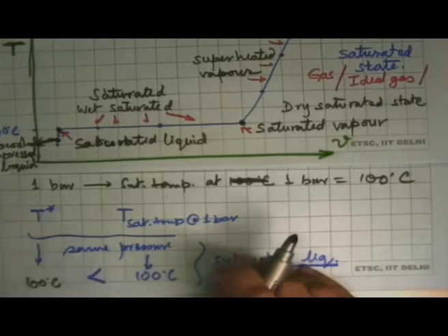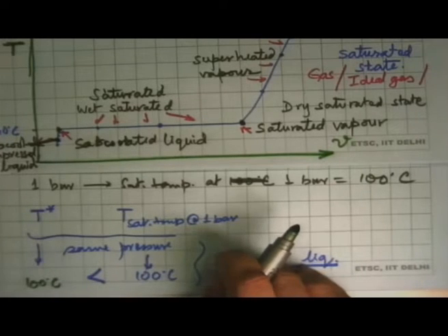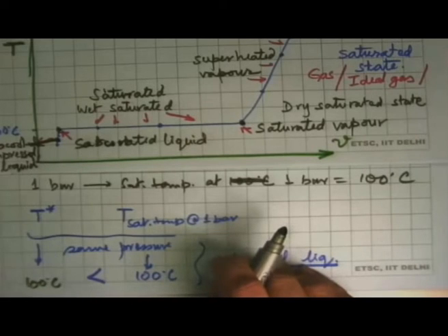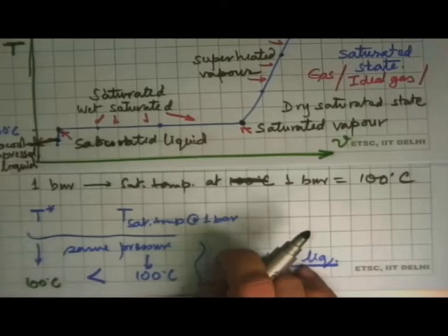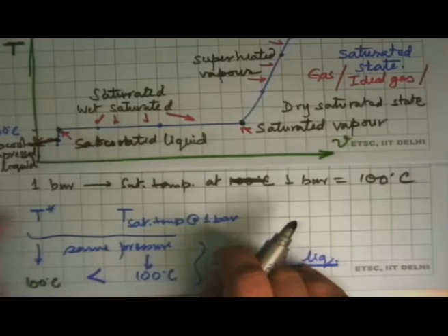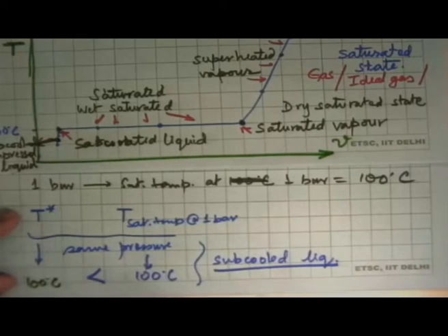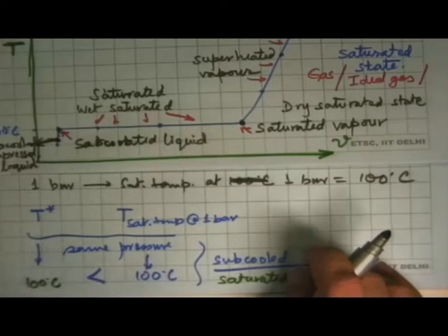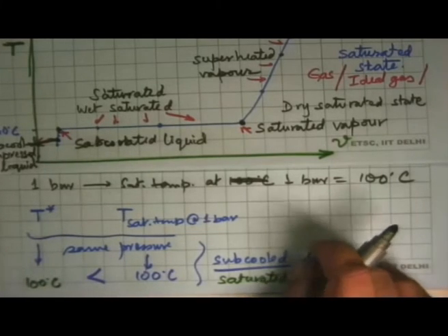And that's why you keep seeing bubbles coming out, because its temperature is not going up. You can make the gas stove or the electric heater as big as you want. The temperature is not going to go up, only the liquid will keep becoming vapor, and finally everything will disappear. So what we have produced at that point is a saturated state, or a saturated liquid. That saturated liquid became saturated vapor and went and diffused into the atmosphere. That's what happened. Now we look at it in another way.